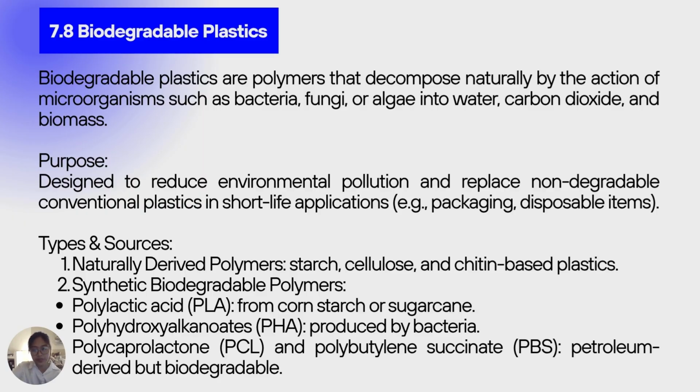Despite their advantages, biodegradable plastics still face several major challenges, such as higher costs. Production often involves fermentation or specialized raw materials, which increases the price compared to petroleum-based plastics. There are performance limitations. Lower strength and heat resistance can restrict use in structural or long-term applications. Composting infrastructure is another issue. Effective biodegradation requires controlled environments, which are not always available in every country. And lastly, public misunderstanding. Some people assume biodegradable means it can safely be littered anywhere, but in reality, most types still require industrial composting to fully break down.